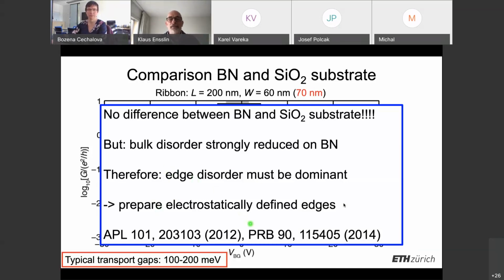So, you know, yesterday I told you about gallium arsenide and silicon and so forth, where these quantum dots are defined electrostatically. And of course, everything that is done electrostatically is sort of smooth because it's defined by electric fields. And while the gate electrodes themselves are, of course, also produced by top-down technology, so they have rough edges, all of these electric fields, they're screened out and they become smooth once they arrive at the location of the quantum dot itself.